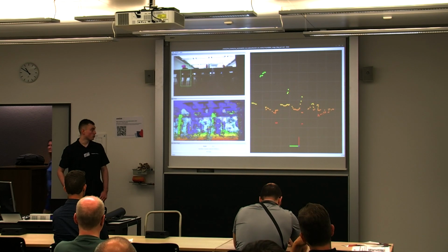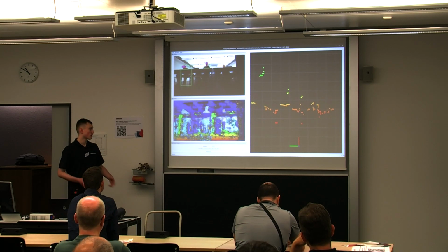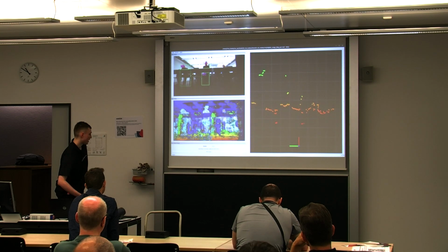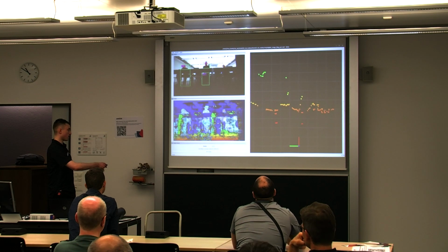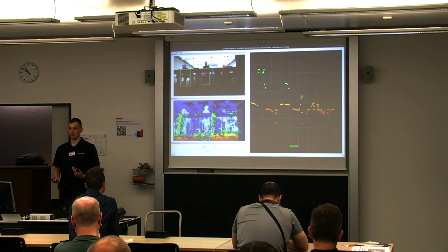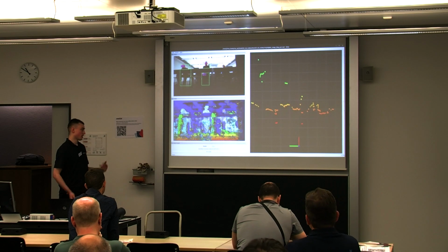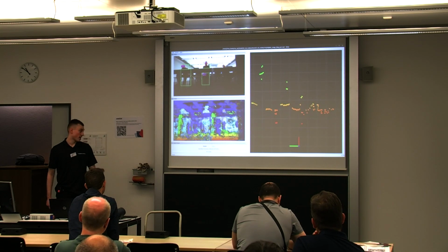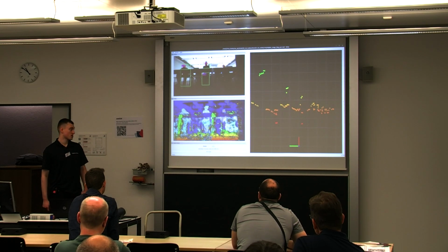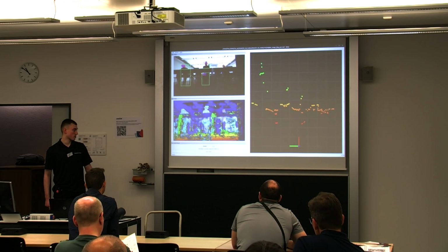On the right, you can see a point cloud. So this is really a top-down view, and you can see for a few select points how far, again, they are away from the camera. So this is also part of our ranging demo. And there's also this heartbeat panel. So we are also running a QNX guest on top of our hypervisor. And this has a heartbeat component, and it sends for every second a heartbeat. And here you can see this has been running for almost 9,000 seconds. And I could actually kill this guest and then see it restart. And what's important about this is that all of the other computation or the visualization wouldn't be affected by this. We could show this if I would kill the guest.